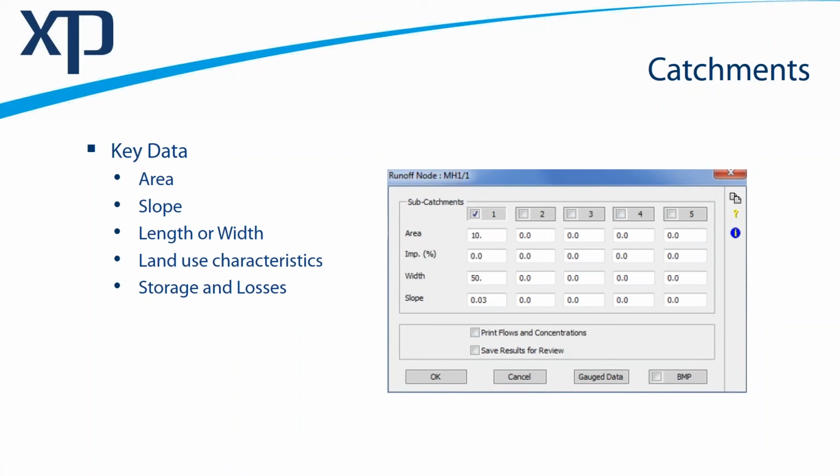You may have, when I gave a presentation last week, the comparison for storage went from small puddles on the ground to dams. And so it's two opposite ends of the spectrum, dams to puddles. But those storages all have an impact on your calculations and affect your losses. And the typical losses, I think I've got a slide on this, include things like infiltration, losses to the groundwater, evaporation over time, pan evaporation from your dams,